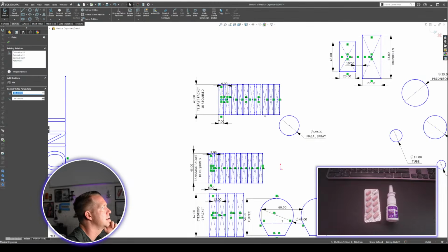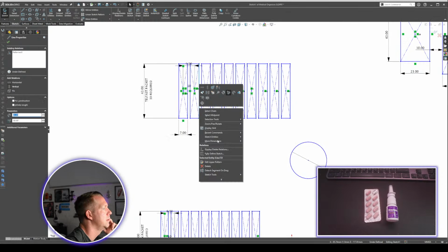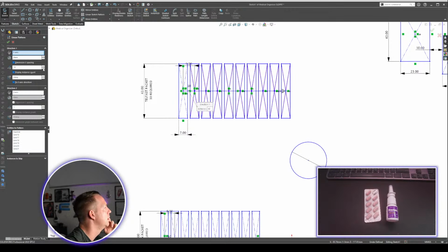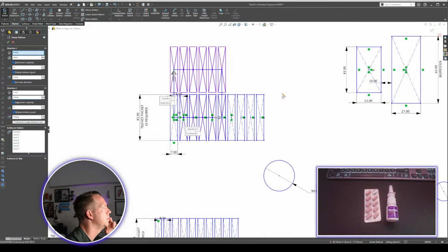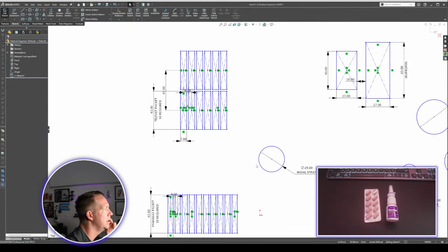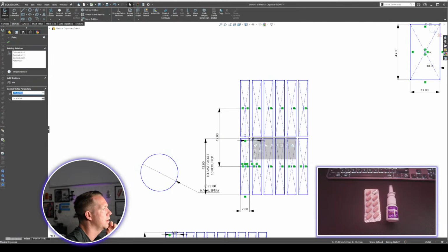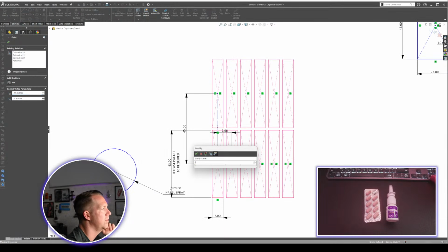If we talk about this slide here, so let's go and edit it now. I'm going to edit the linear pattern. I'm going to reduce the number to 6. I'm going to add a second number. I'll go this direction, 43, so I want that to be 45. Press OK. It's updated that sketch for me. And so what my plan is, actually I'm going to change that again, but this time I'm just going to change the number. So I'll change from a 6 to a 5.